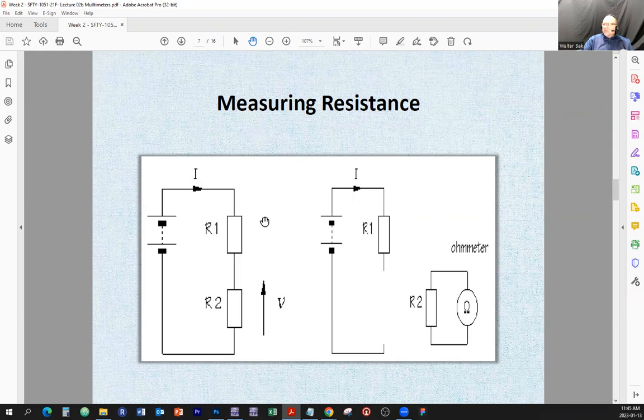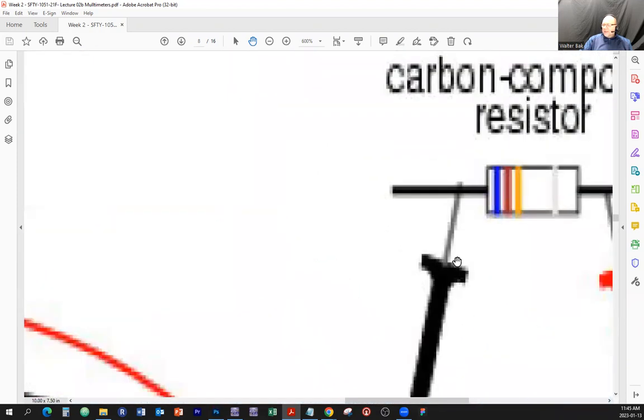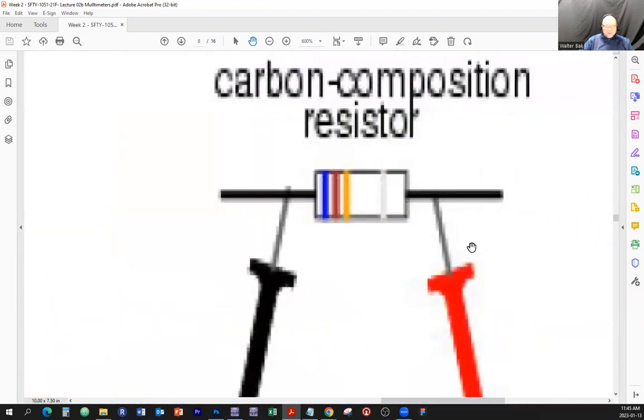So measuring the resistance, you have to make sure that you remove the component. And I said one leg, lifting one leg is just enough. So that's measuring resistance of a resistor. You got to make sure that when you measure the resistance, sometimes you're going to hold the whole resistor and the leads, and just remember your body has a certain amount of resistance between your two hands.